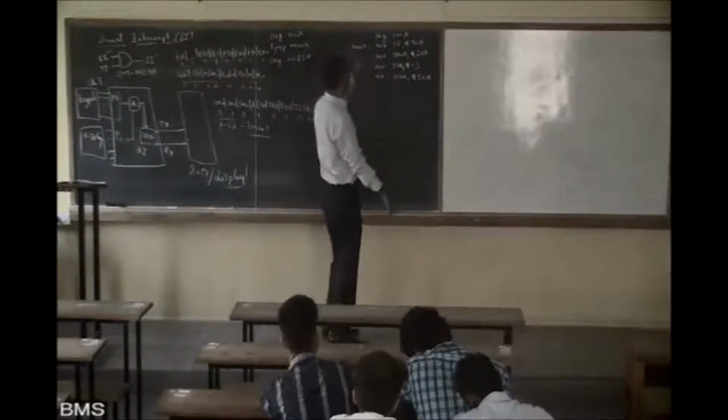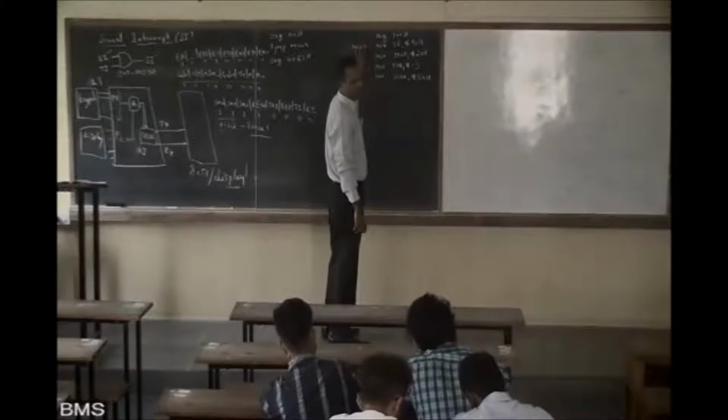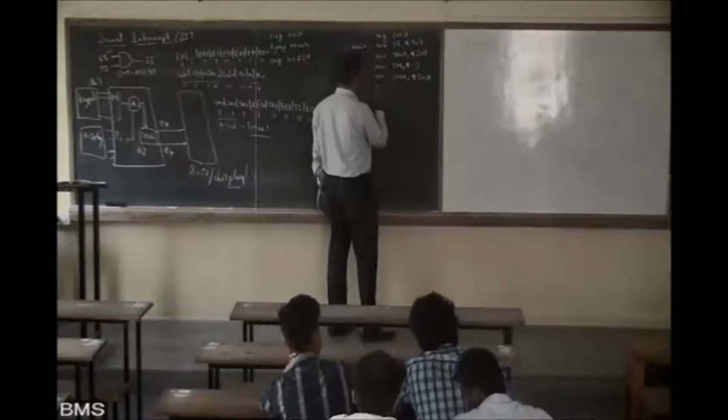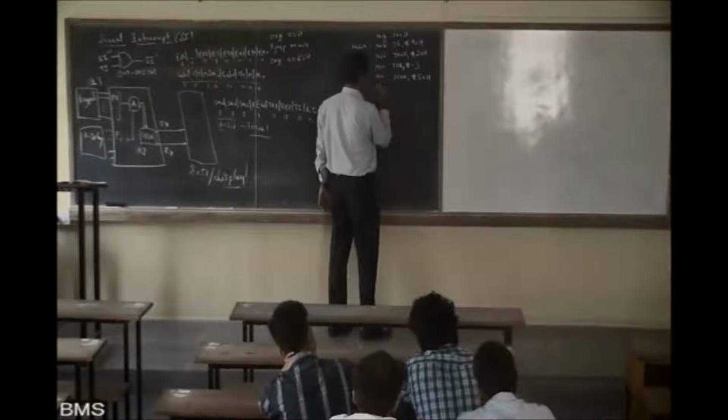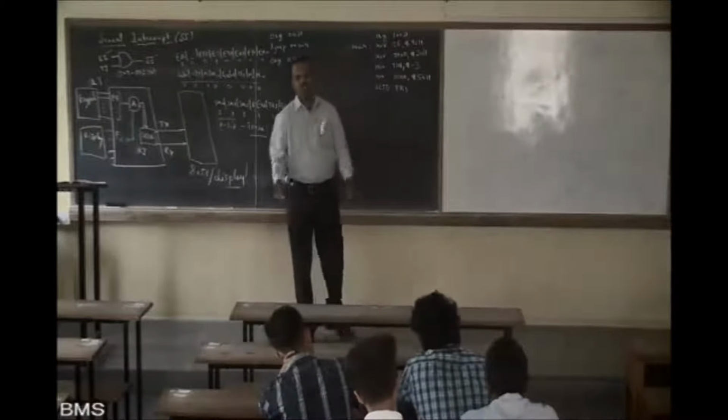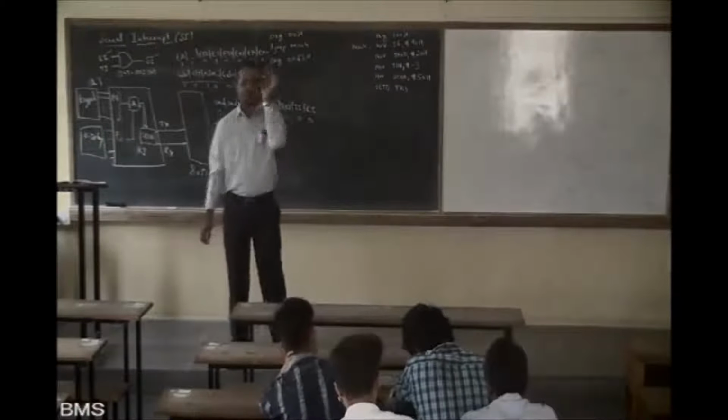Serial communication is ready. Interrupt is enabled. Baud rate is ready. Next, what should I do? Start the timer. Set bit TR1. Timer started. So baud rate started now. Now next what?